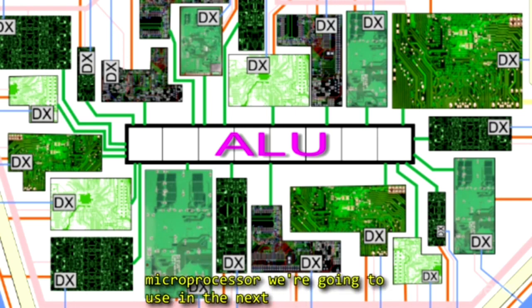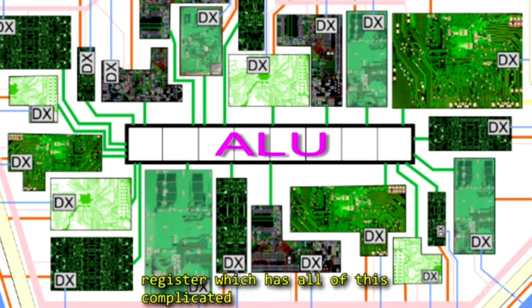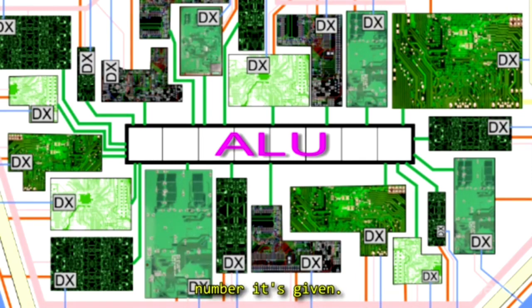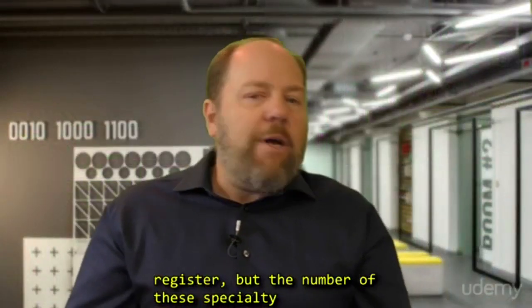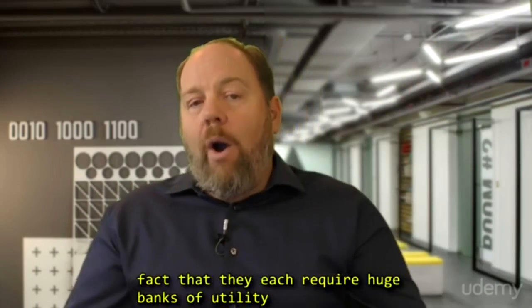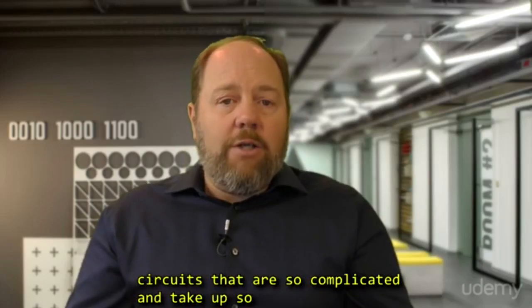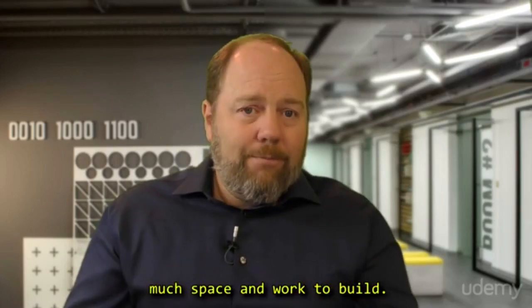So in the microprocessor we're going to use in the next lesson, they call it the working register. So whatever name it goes by, this specialty register is the register which has all of this complicated circuitry attached to it, so it can manipulate the number that it's given. Now, some microprocessors have more than one math register, but the number of these specialty registers is always a small number for the simple fact that each require huge banks of utility circuits that are so complicated and take up so much space and work to build.